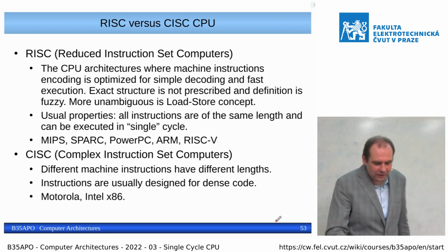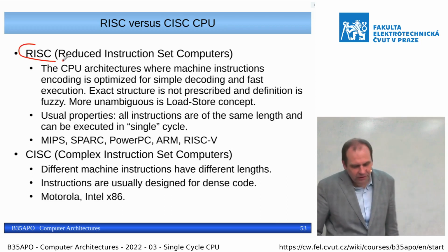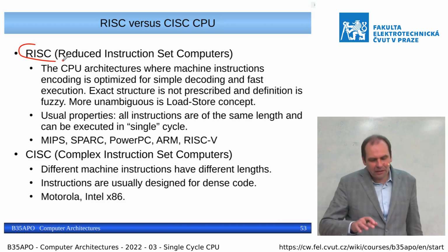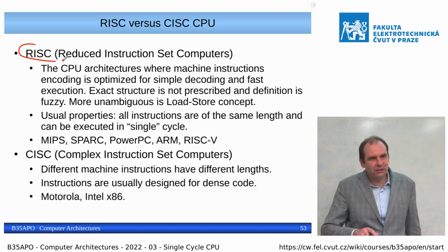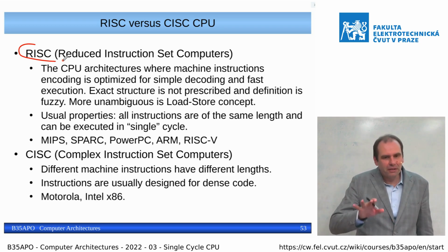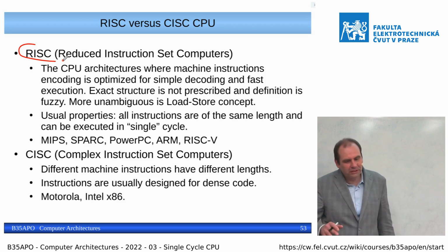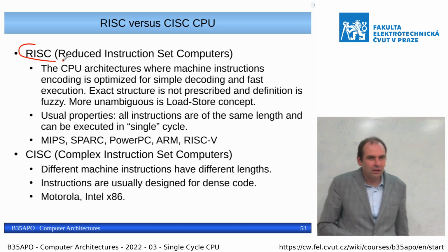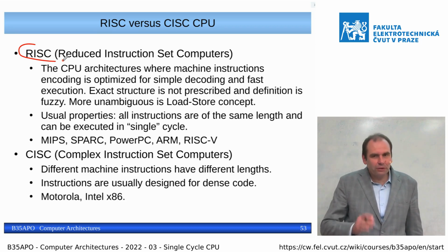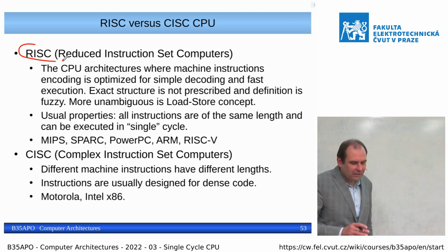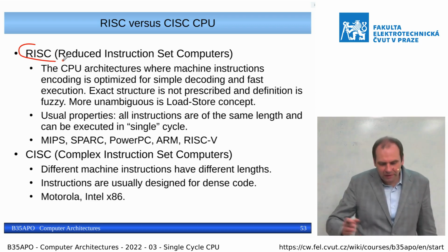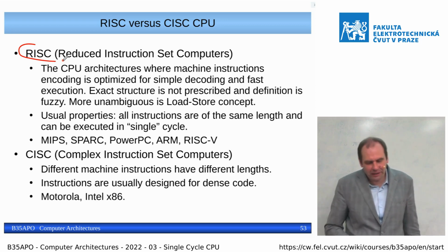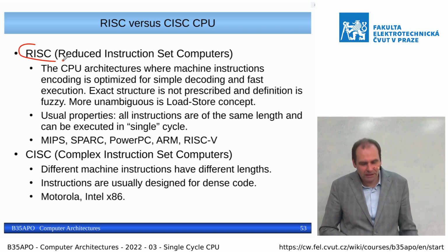Okay, so this is a difference between reduced instruction set computers, which in fact return back to the time when bits encoded directly inside the instruction activate the data path and the units inside through some simple table, and it is not necessary to process and decode the instruction in multiple cycles. We then switch to the pipeline variant, where we start to execute some parts of the instruction one after another, but the actual decoder is very simple, and the attempt is to have it defined exactly only by that single table.